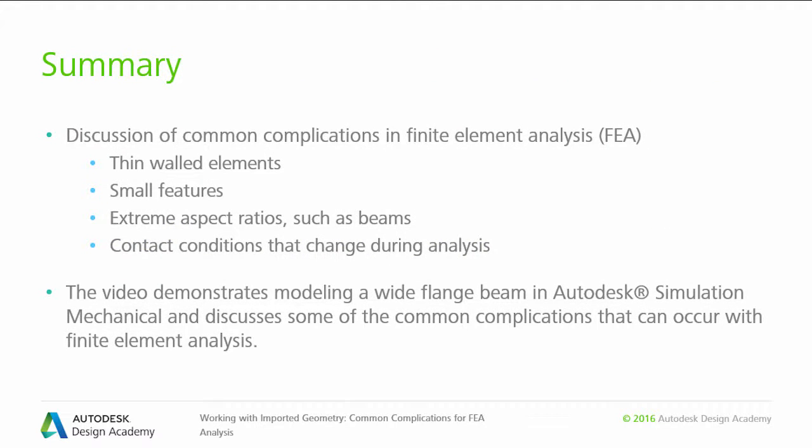In summary, we have discussed common complications encountered in FEA, including how to handle thin features, small features, extreme aspect ratios, such as beams, and contact conditions that change during the analysis. The two-part video demonstrated a comparative analysis of a beam using 3D solid and 1D beam elements.